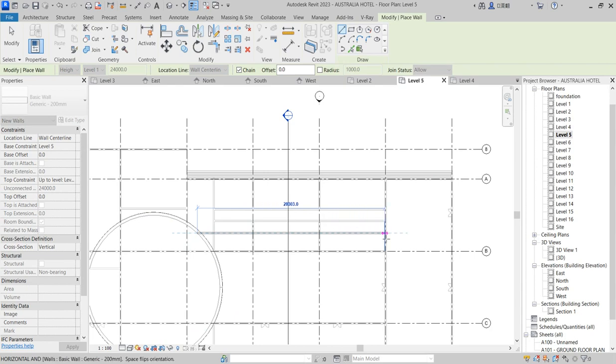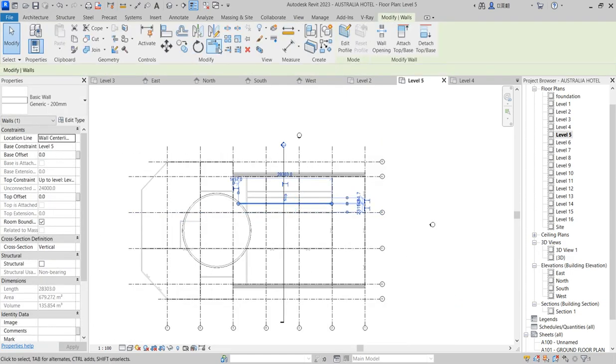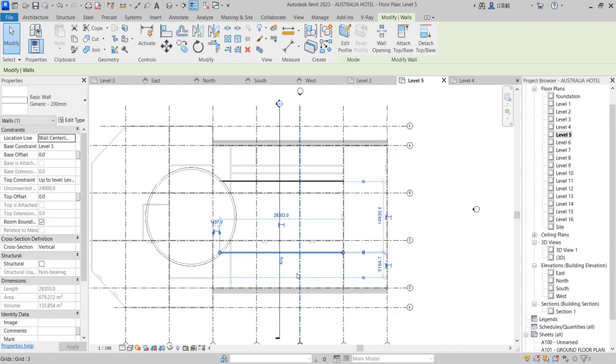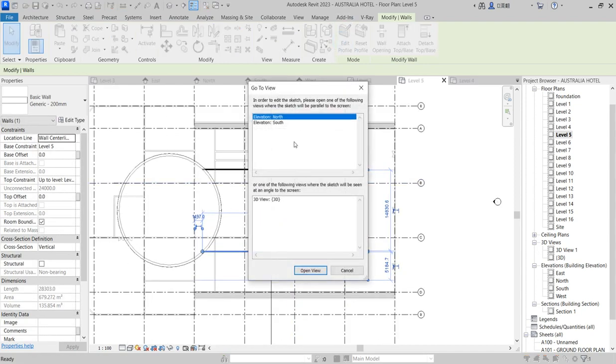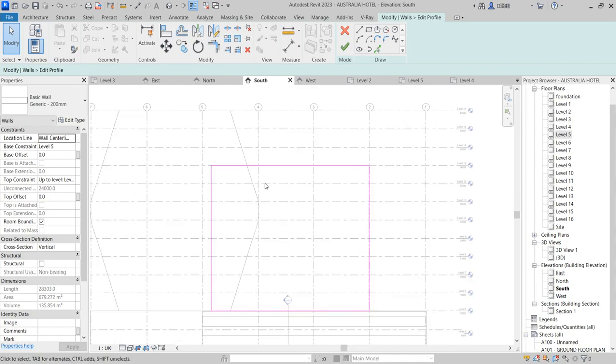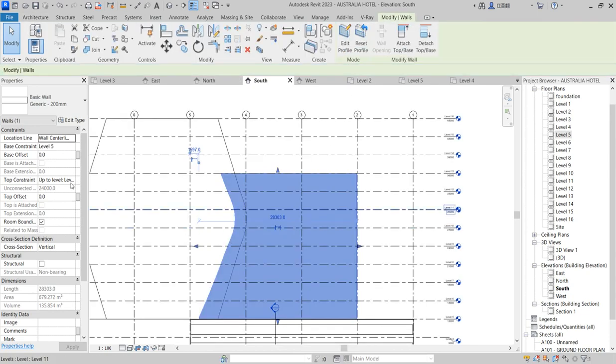So I'm drawing this to this point. So then from here I will mirror this, or wait, yeah, mirror it. So when you mirror this, good. So edit this profile, only this profile, because you still mirror it back. So go back here and see edit the profile. So the profile will be editing at this level. So actually the level I want is at level 14. So I'm still going to work on that one. So click finish and change the level to level 14.